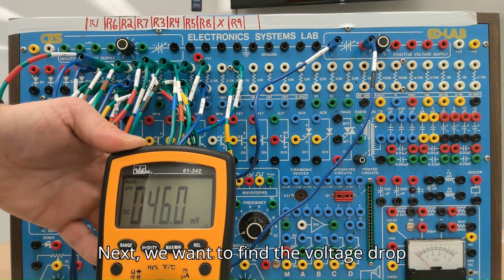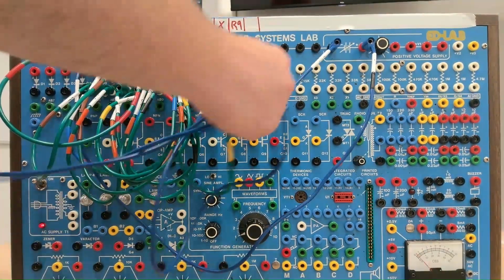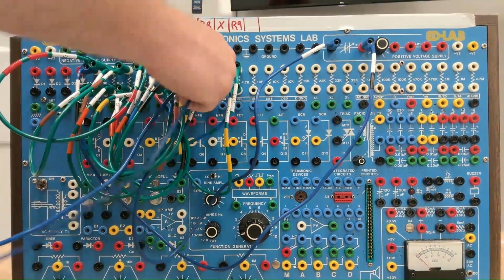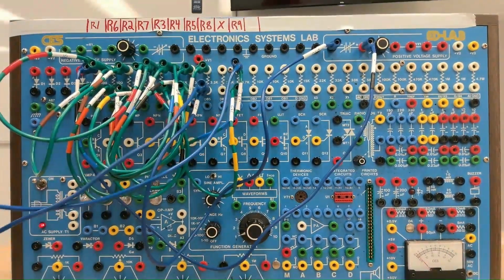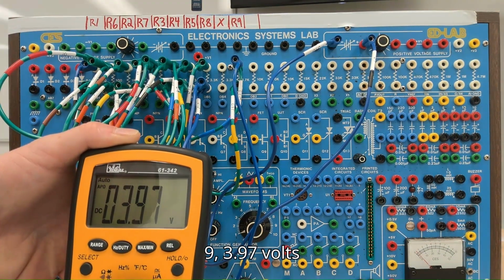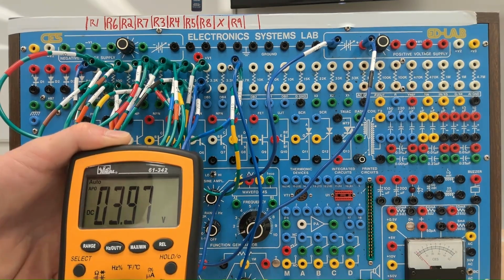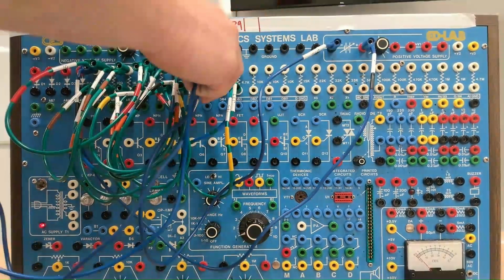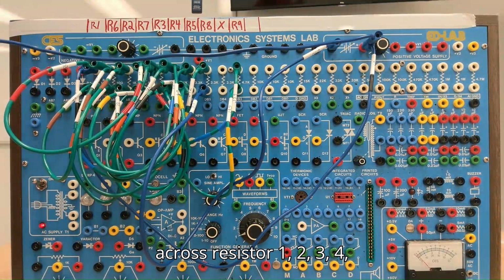Next, we want to find the voltage drop across R8, R9. The voltage drop across R8, R9, 3.97 volts or 3,970 millivolts. The next measurement we want to find is the voltage drop across resistors 1, 2, 3, 4, 5.